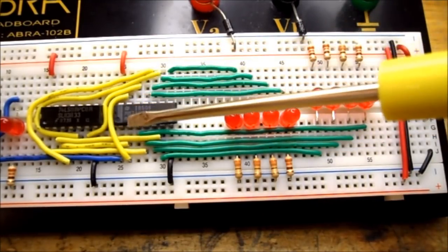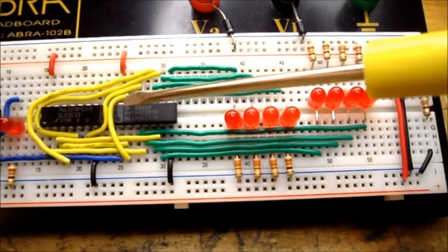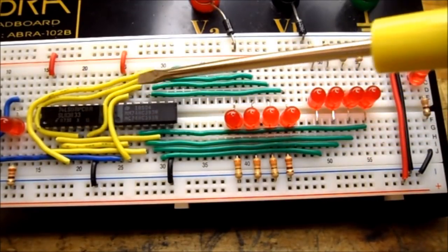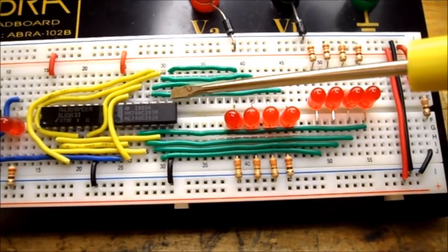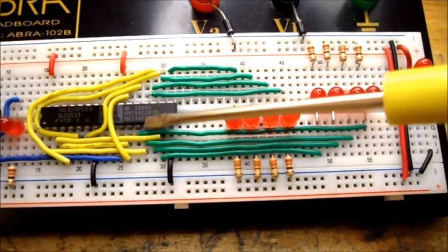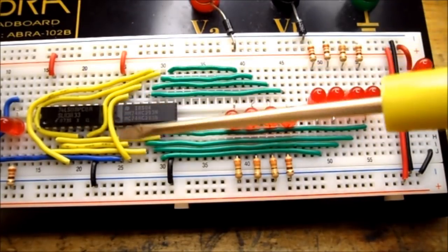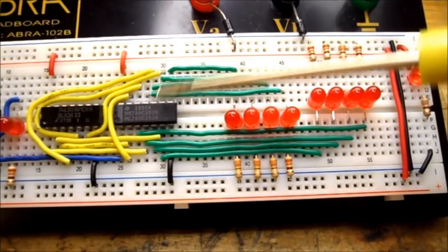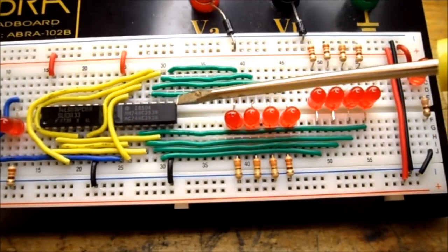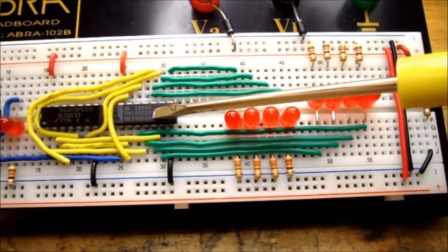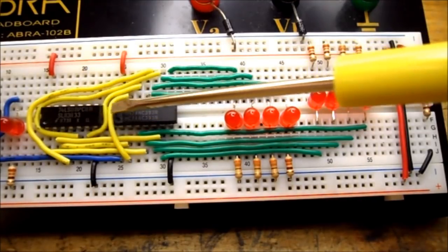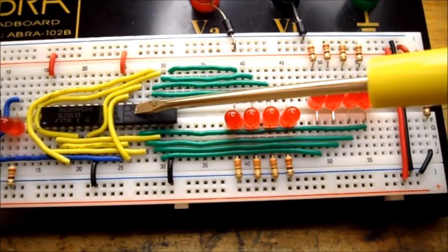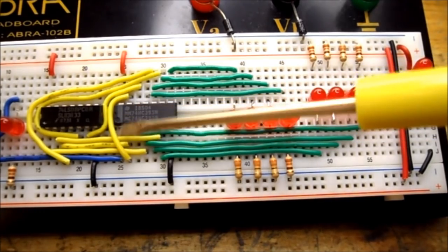Also notice I don't have any wires crossing my ICs. A lot of times you guys tell me I've got a bad IC. When we go to replace it, we have this great big bunch of wire going across all your ICs that we have to separate to put in a new IC. So if anything's wrong with my ICs, they're easy to pop out and replace without having to move a whole bunch of wires.